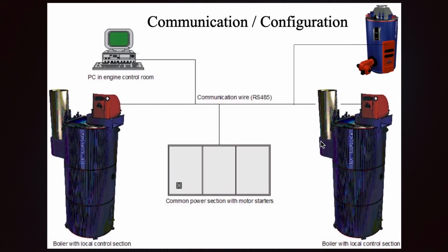So it will start from 0 to 15, let's say, load, and in the beginning you will have the purging, and your air fan will operate from 0 to 70 to make the purging. So you will see that your system is working, but your moving parts will slowly be worn by time, and you will see some mechanical failure problems, which can be associated with moving parts, some rollers on the fan on the top, and some looseness on that.